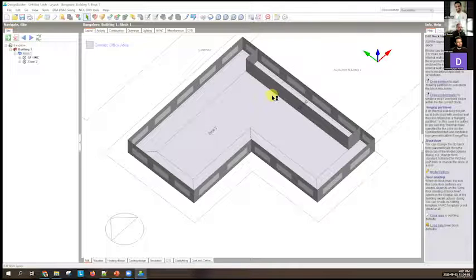Now, if you're interested in air conditioning, typically an air conditioning engineer will split a floor into perimeter zones that are next to the external wall, and a center zone or an internal zone, which is not connected to any of the external walls. And there's a reasoning for that.